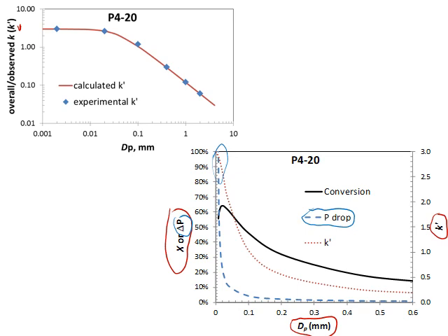At very small particle size, you can see that the pressure drop is very large, and therefore the conversion is not as large as it could be. Now let's look at very large particle size. I have solved the problem of pressure drop; the pressure drop is less than 2%. But the problem is with the K prime. The K prime is very small. Why? Because the internal diffusion faces large resistance, large limitations. Therefore K prime becomes very small, and the conversion is very small. So at very large particle size the conversion is very small, and at very small particle size the conversion is also small. There is an optimum solution somewhere in the middle. This is the optimum particle size where conversion is at its maximum value. So with this we finish this problem. Please look at it carefully at home.